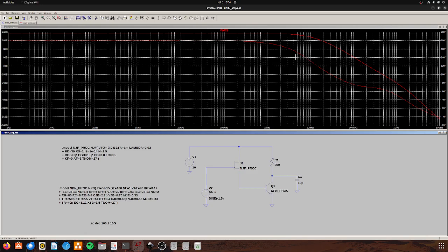So this is a more real AC response. You actually have a bandwidth of close to 100 megahertz, which for the power it consumes is very bad actually. It's actually consuming a lot of current. Again, by checking this, it will reduce a little bit of the frequency.